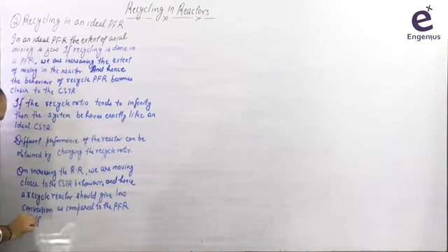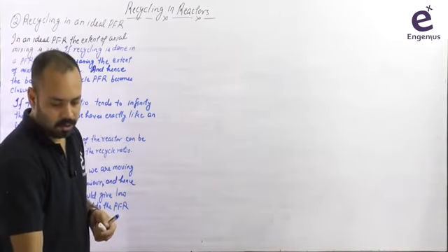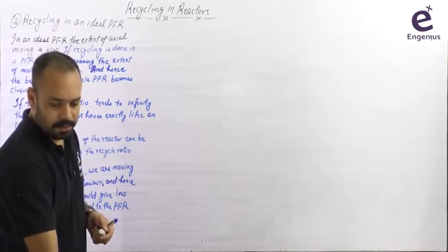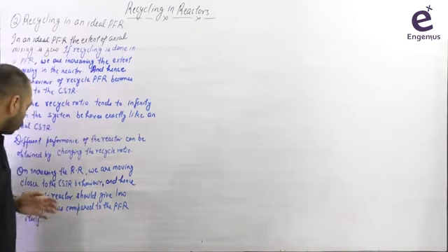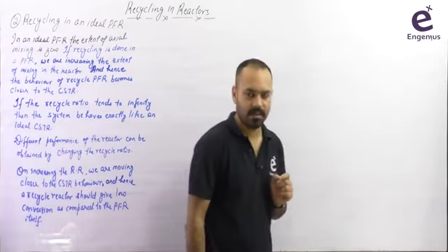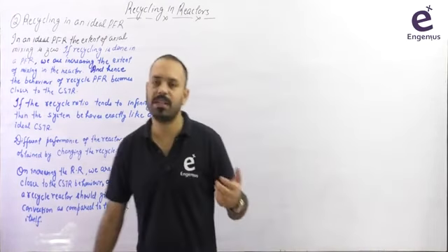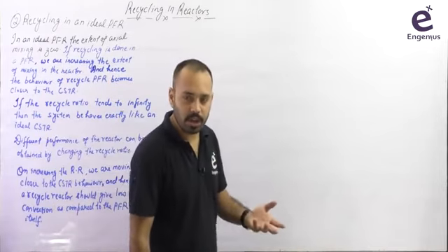I'll give you the numerical explanation, the theoretical derivations also. Fine. So what is the extent of back mixing? What is the extent of this recycle ratio in your recycle PFR? In that case, you can control the behavior of your recycle reactor. But now the question arises that if on increasing the recycle ratio, I am moving closer to the CSTR behavior, then it means that the conversion obtained now at high recycle ratio will be low.